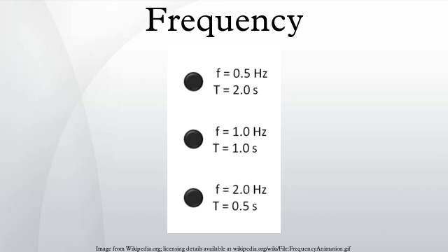This error decreases with frequency, so it is a problem at low frequencies where the number of counts n is small. By stroboscope: an older method of measuring the frequency of rotating or vibrating objects is to use a stroboscope. This is an intense repetitively flashing light whose frequency can be adjusted with a calibrated timing circuit.